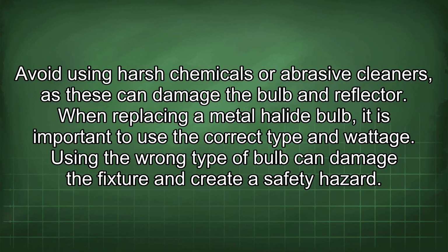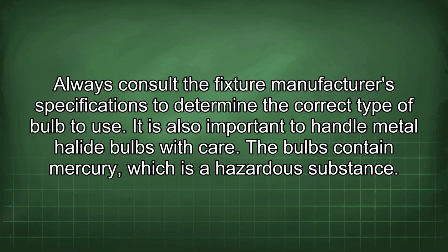When replacing a metal halide bulb, it is important to use the correct type and wattage. Using the wrong type of bulb can damage the fixture and create a safety hazard. Always consult the fixture manufacturer specifications to determine the correct type of bulb to use.